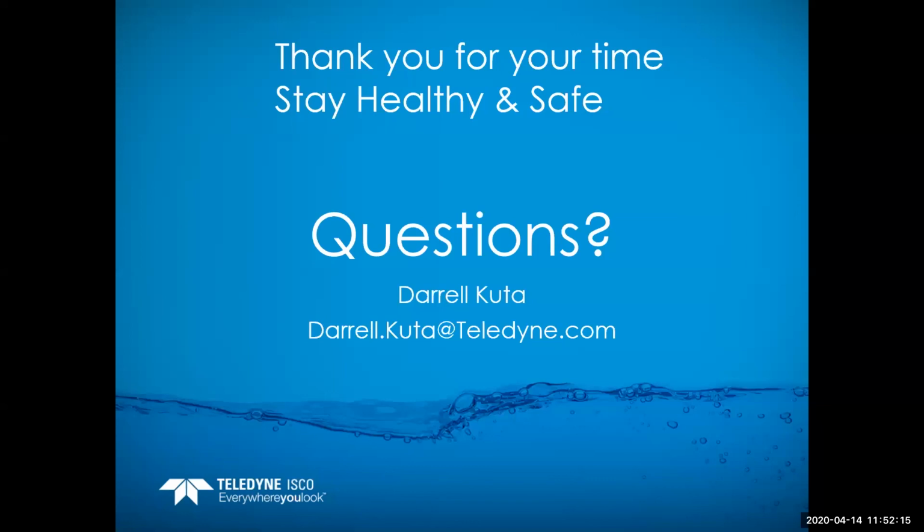Somebody else is asking what's the recommended maintenance schedule on laser flow units and what does it involve? That's a tricky question. We do not have a specific maintenance schedule that we recommend for it, because it's all site specific. If you have an application that tends to build up debris in your channel, you're going to have to go and check on it more often to calibrate it.